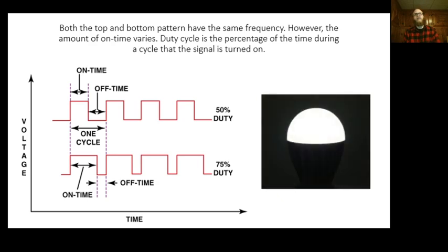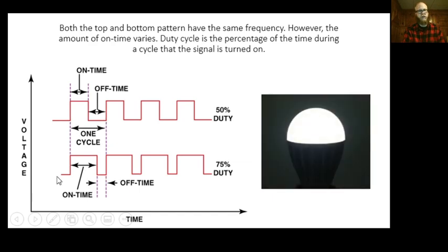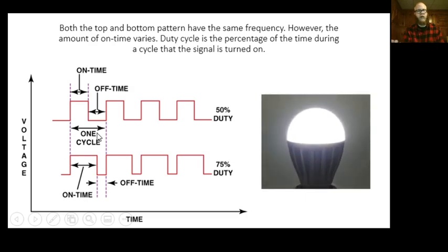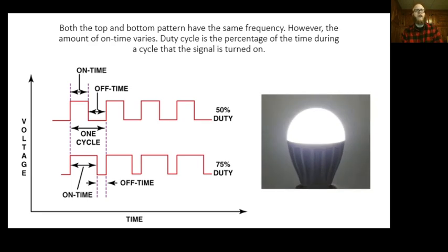When we get into duty cycle, what that means is, let's say this wave, see how my total one cycle is the same regardless, right? So hertz, that's one cycle per whatever percentage of a second. The number of times this happens would actually give me my hertz rate. So like in the wall, our AC current, alternating current, has a hertz rate of 60. It cycles from positive to negative to positive to negative to positive to negative. It does that 60 times a second, so 60 hertz.